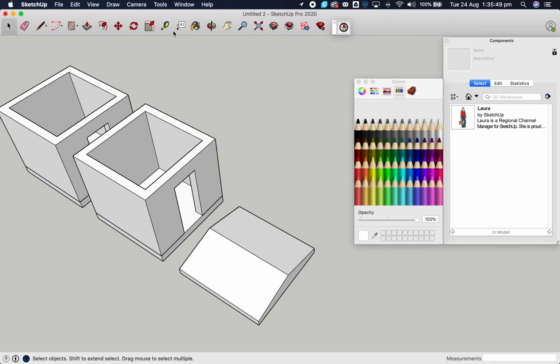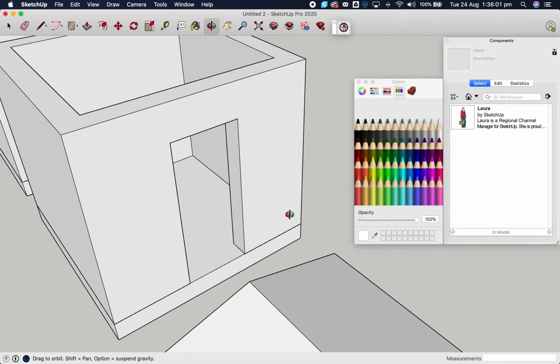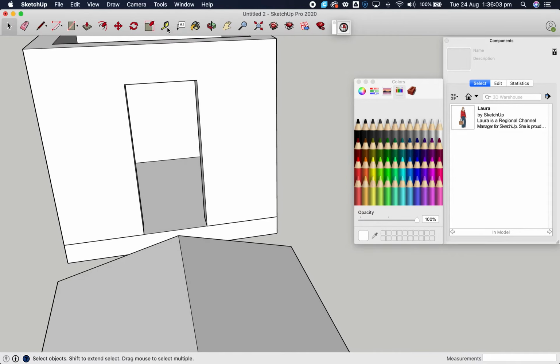Okay, so let's check this by measurement. This should now be 33 millimeters. Yes, and it is. Okay, so now that is correct. Other things we need to do: we need to see this store here, and let's measure the width of this store. Now this could be a window or anything like that. Now 10 millimeters is too much of an overhang for the 3D printer to manage.